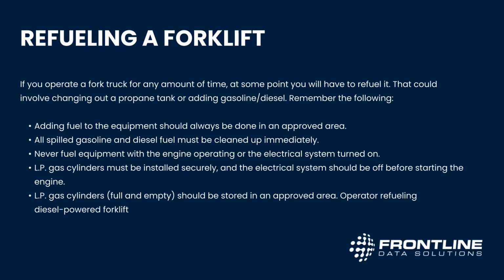At some point, forklift operators will need to refuel, whether that means changing a propane tank or adding gasoline or diesel fuel. Fueling should always take place in an approved area, and any spilled gasoline or diesel must be cleaned up immediately. Equipment should never be fueled while the engine is running or the electrical system is on, and LP gas cylinders must be installed securely and stored in an approved location.